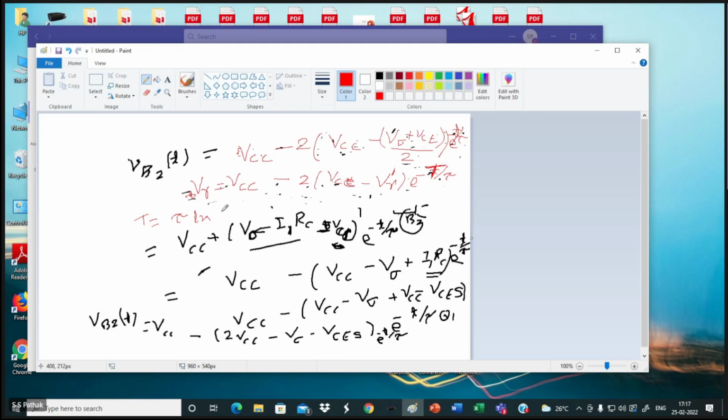So it will be DC only, so it will be a plus, minus like that. So from here, this was my R. So it is charging through a current, okay, and that is passing through this R plus RC1TH and C. So your tau is nothing but R plus RC1 Thevenin's equivalent resistance